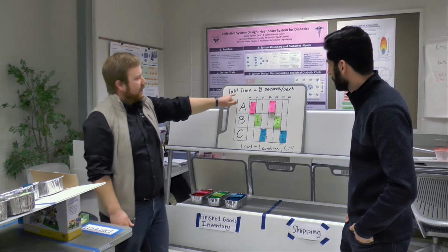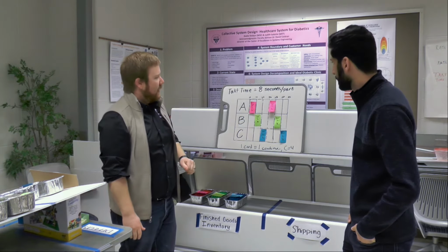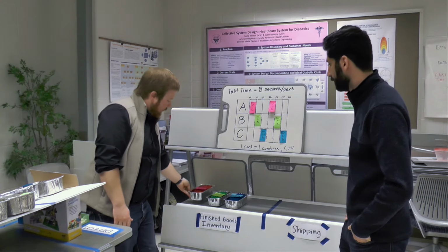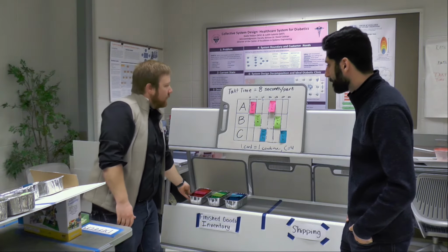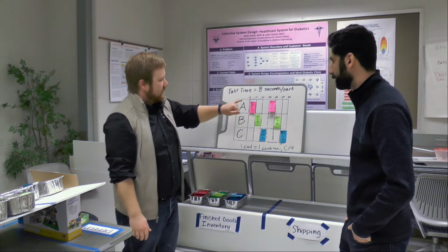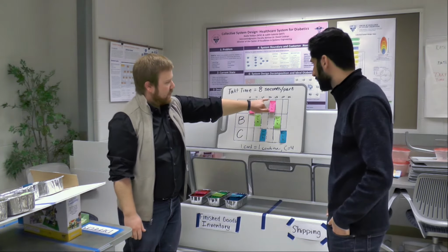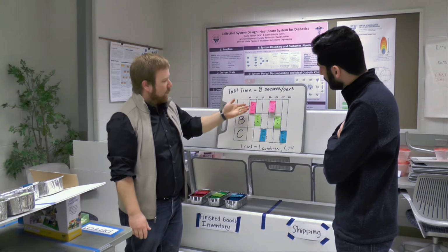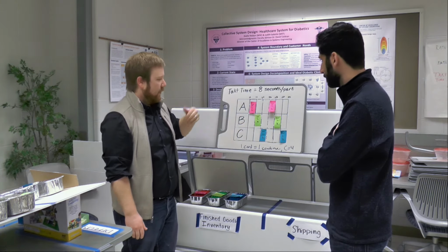We've labeled our takt time as 8 seconds, and we have a pitch of 32 seconds because we have 4 in a container times our 8 seconds, which gives us these 32-second pitch intervals. So at every 32 seconds, I will pull a card off of the Heijunka box.